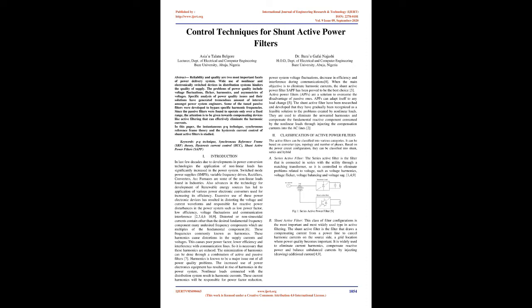Introduction. In last few decades, due to developments in power conversion technologies, the application of nonlinear loads has significantly increased in the power system. Switched mode power supplies, SMPS, variable frequency drives, rectifiers, converters, arc furnaces are some of the nonlinear loads found in industries. Also, advances in the technology for development of renewable energy sources has led to application of various power electronic converters used for increasing its efficiency. Excessive use of these power electronic devices has resulted in distorting the voltage and current waveforms and responsible for reactive power disturbances in the power system such as low power factor, low efficiency, voltage fluctuations, and communication interference.